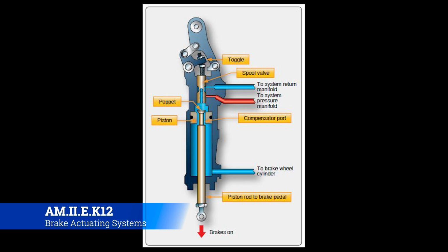So effectively, as you're taxiing around, you can hit your toe brakes, and it works just like an independent brake system. And let's say you're going to land, and you really need a lot of extra oomph to get that aircraft stopped, you can press just a little bit further. It opens that spool valve. You get a lot of extra pressure pushing down on the brake cylinder, and it will help the aircraft come to a complete stop. This one's a little bit more rare, I'd say. Most of them just use hydraulic pressure for brakes, and you kind of bypass this whole thing, but you could encounter it.